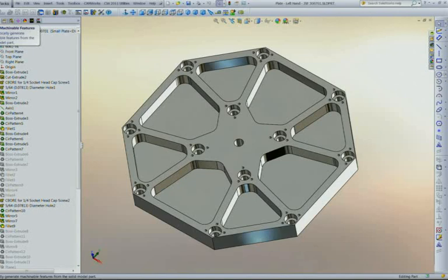Hey, Mark, I want to mention something about that too. Remember, in SolidWorks we have things called features, and the features that we talk about in SolidWorks are design features. So you'd extrude, you'd create a fillet. But the features that Mark is talking about when you use automatic feature recognition, he looks at a part like this, and that pocket, which might be an extrude with some fillets on it, CAMWorks sees that as being a pocket feature. So the features that Mark is talking about are manufacturing features. I just want to make sure that's clear to everybody in the audience. Sure. These are machinable features that we're going to extract automatically.